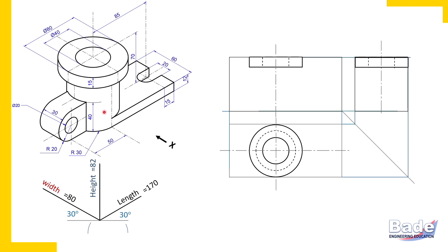As usual, in the top view a circle, the remaining 2 views rectangles. Let's do that. So here the circle in the top view, dotted, we have already drawn. Now I have drawn end projectors, and here the cylinder is complete. And now draw end projectors from the top view to the side view, and you will get the corresponding rectangle in the side view.